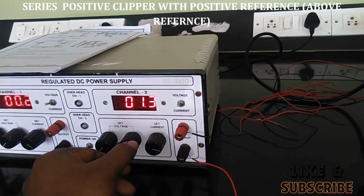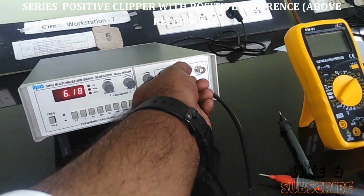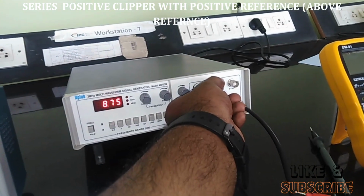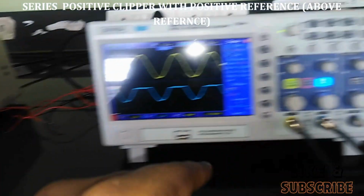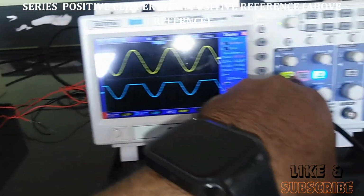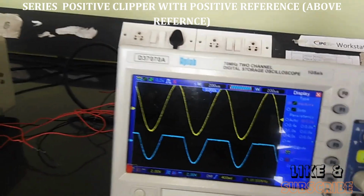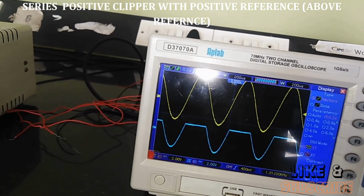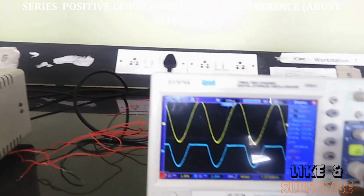And as per the circuit diagram, I'm going to set 10 volts peak to peak here. How to set 10 volts peak to peak? I need to increase the value for 10 volts, and I'm going to check the input value, only the input value. I'm going to check the input first.